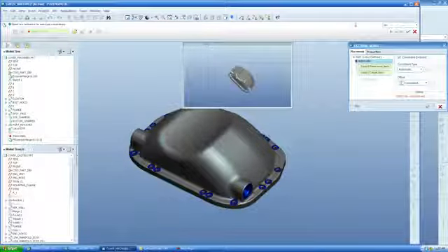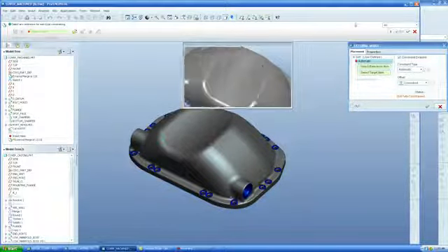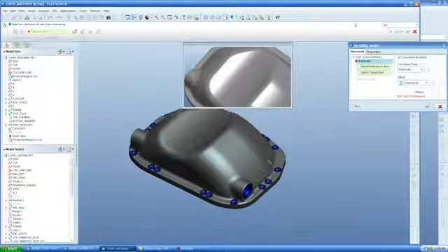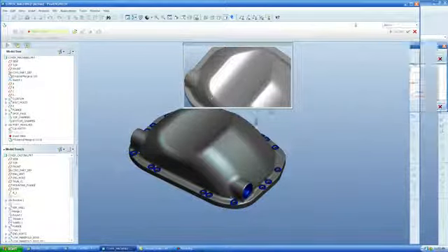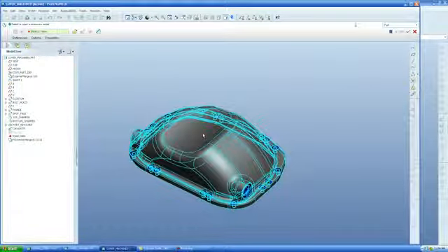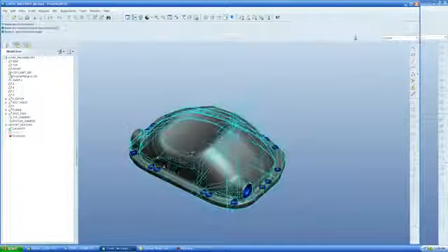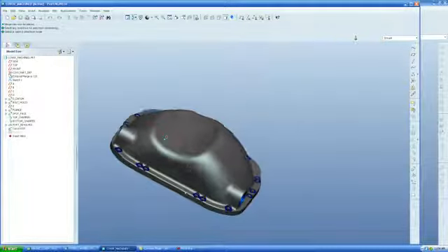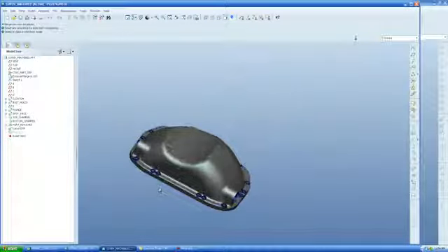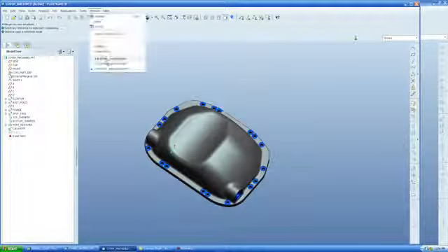You'll see it brings up a window here. This is my casting in this window. This is the first part in this part file. So what ends up happening is whenever I change my casting, it updates here. And the only thing I care about in my machine model is that I have my cuts for my machining. It makes for an easier drawing when you go to do your machine drawing. So that's typically why I set my models up that way.